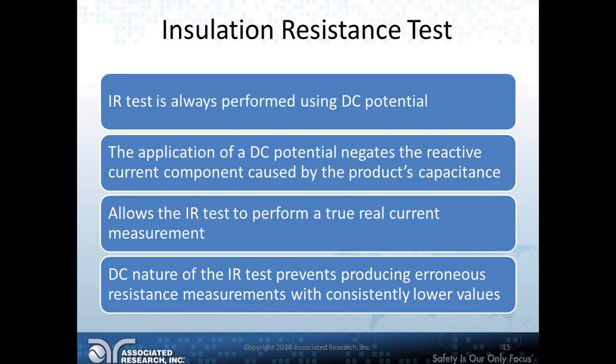Now, a lot of people who perform the insulation resistance test may not have heard of this term, the polarization index, but as these dipoles align themselves, absorption current is created, which decreases over time. Initially, this absorption current is high, but as fewer and fewer dipoles are left to align themselves with the applied field, the current drops. Therefore, an insulation resistance measurement taken after 1 second could yield a lower resistance than an insulation resistance measurement taken at 60 seconds.